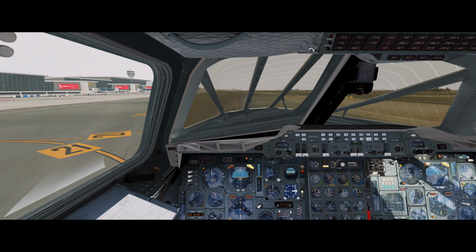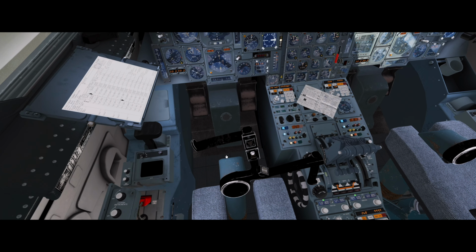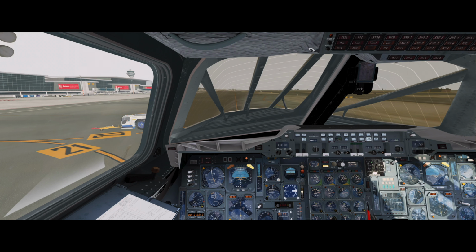Nose wheel steering. Okay, it's checked this side. Flight controls, AFCS and trims. They're all checked now. Feel. Yep, that's all engaged. Engine anti-ice, engine schedule. It is off and we are flyover. Brake fans. On. Idle switches. Set to low. Door warnings. Tested and off. Engine feed pumps. They're all on. Hydraulics. Checked.